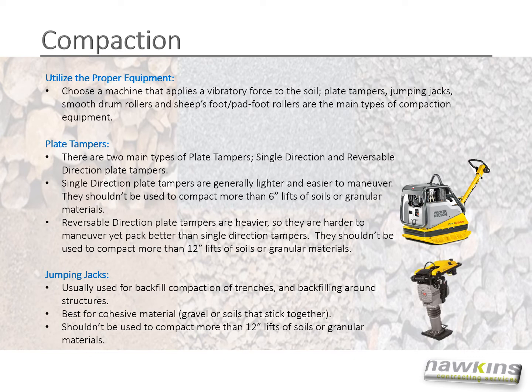Jumping jacks. Usually used for backfill compaction of trenches and backfilling around structures. Best for cohesive material, such as gravels or soils that stick together. These shouldn't be used to compact more than 12-inch lifts of soil or granular materials.